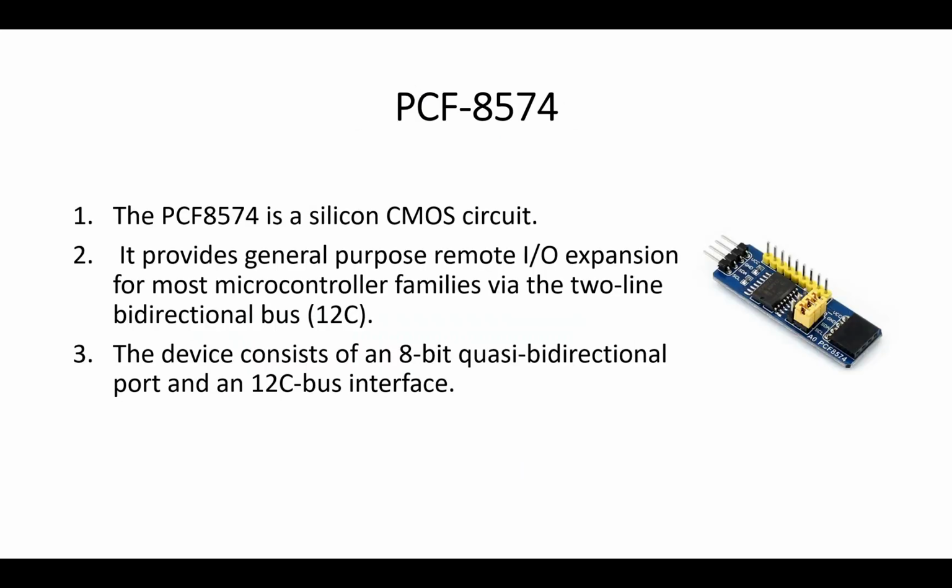This is the figure of the W5500 model. And also we are using PCF8574. It is a silicon CMOS circuit. It provides general purpose remote input/output expansion for most microcontroller families via the 2-line bidirectional bus. The device consists of an 8-bit quasi-bidirectional port and I2C bus interface.